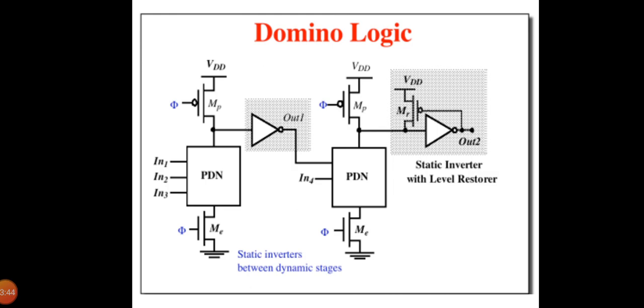Since the inputs to a domino gate are low during pre-charge, it is tempting to eliminate the evaluation transistor because this reduces the clock load and increases the pull-down drive. However, eliminating the evaluation device extends the pre-charge cycle. The pre-charge now has to ripple through the logic network as well. Consider the logic network shown here, where the evaluation devices have been eliminated.